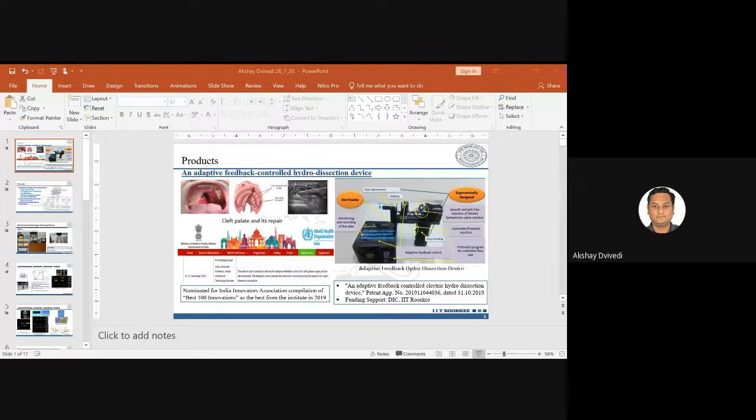The answer is that it is a good approach, but of course, it has certain issues as well. Whenever you coat, let's say, an abrasive particle on an electrically conductive tool, the abrasive is, let's say, silicon carbide. Silicon carbide will not have the kind of conductivity of, let's say, a stainless steel tool or a copper tool. Basically, it will act as a non-conductor, an insulator kind of thing.